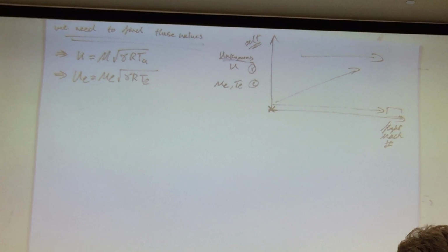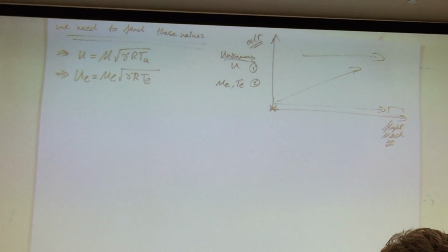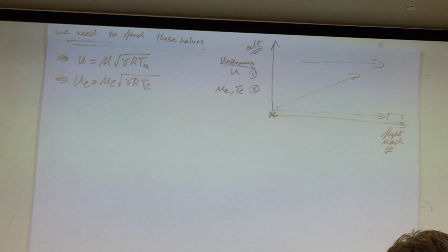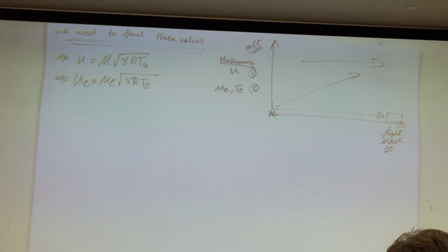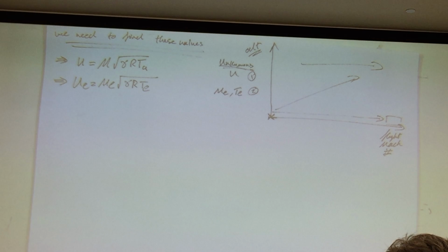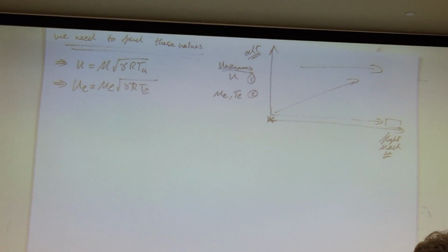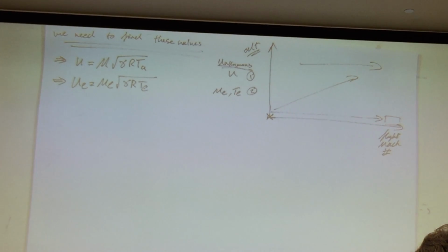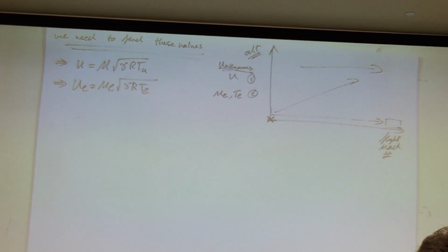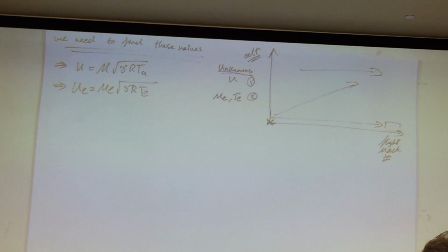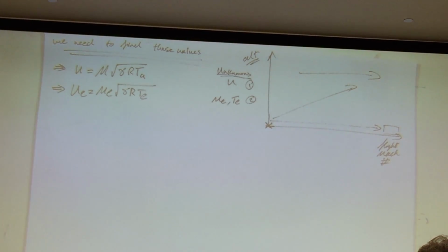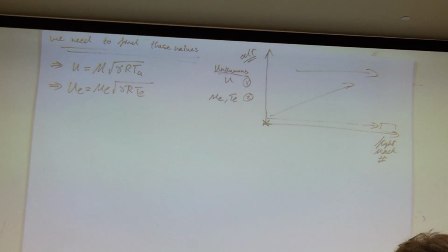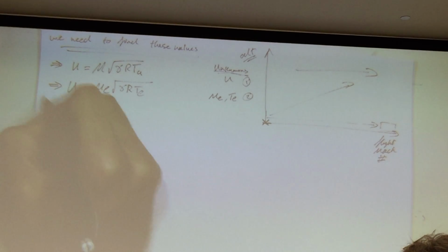Now, depending on the situation, you might be designing it as an ideally expanded situation where your exit pressures are equal, or like the project, but it's not ideally expanded and you have a shock there. And there is a reason why you're designing it based on a shock there, because we are going to add heat addition, and that's going to push that shock away. When you try it with and without ideally expanded versus with the shock there, you will notice that the stagnation pressure is drastically higher. That's what you're getting by just doing that combustion process there. So, anyway, assume ideally expanded.